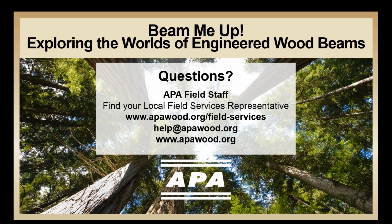So the designer should really consider the conditions. If the beams are fully braced, as they typically are when installed on a floor where the joists brace the beam, either choice is great. But if the beam is not fully braced, the designer will need to check that unbraced length may be different between a built-up member and a solid member, as the solid member may have a longer unbraced length when compared to built-up beams. So that needs to be checked.